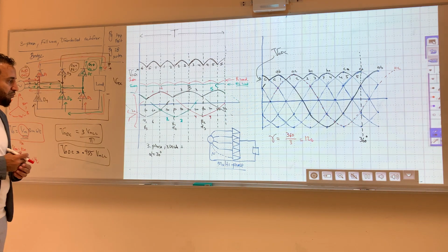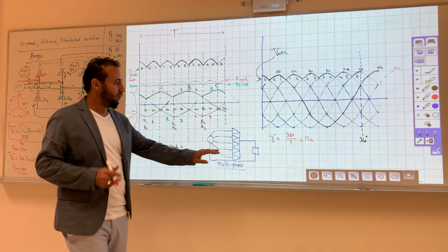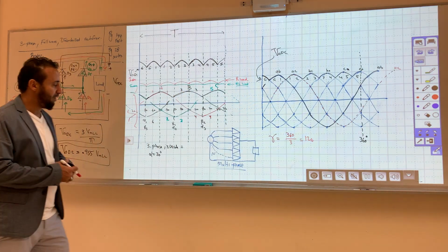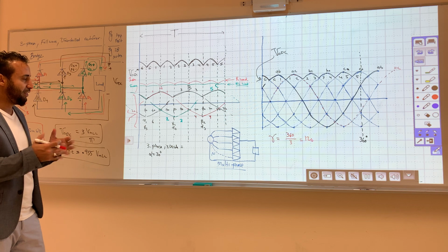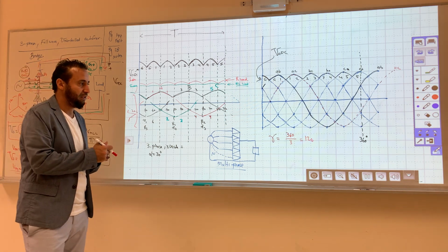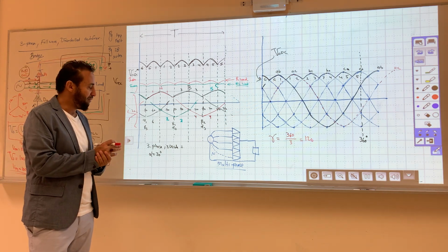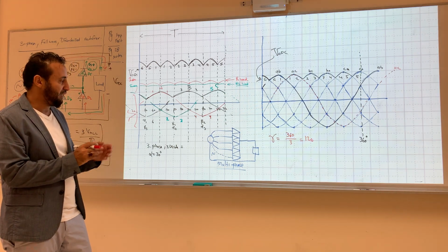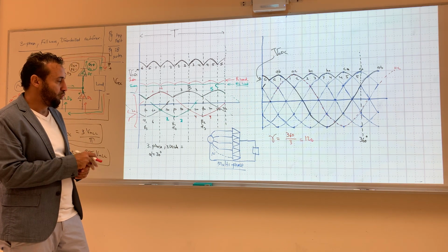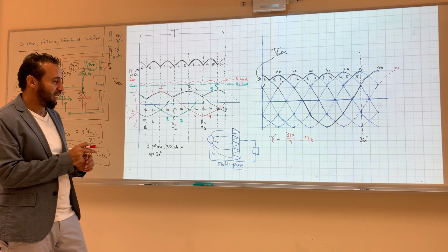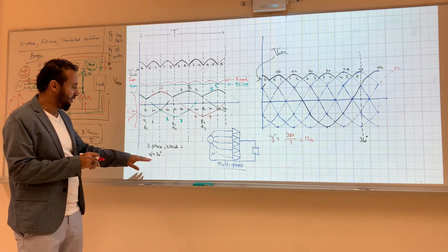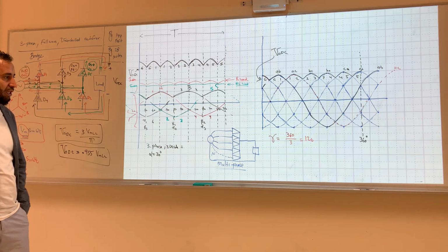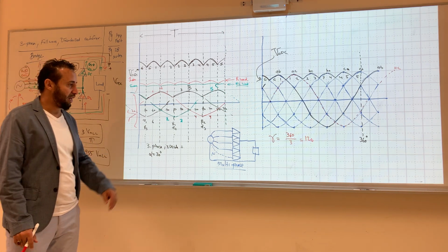Here I know the conduction angle, which is 120, and I know the alpha, so this will be my reference, guys. This will be my reference to find the alpha now. I have the conduction angle, which is 120, and I know the number of diodes, which is 3, and I know the alpha right here.